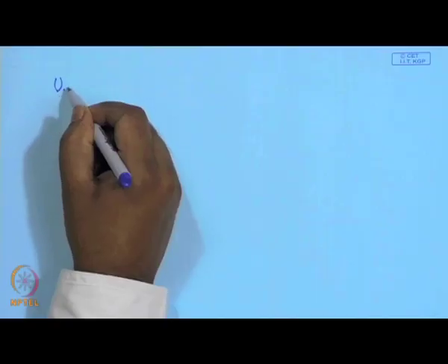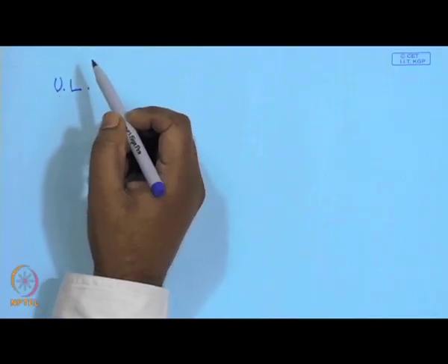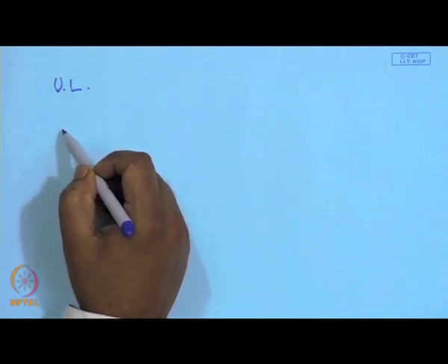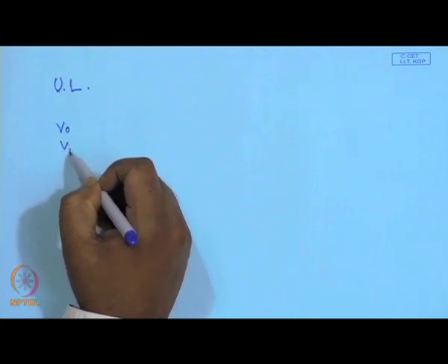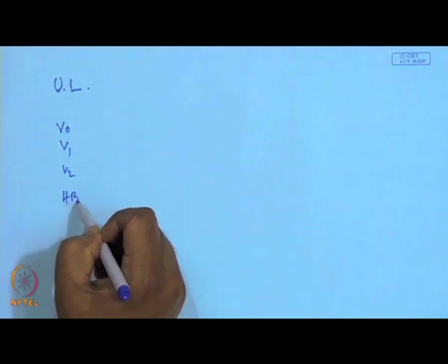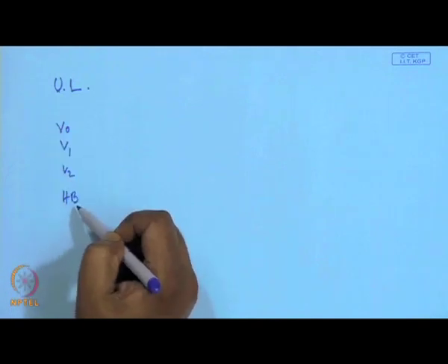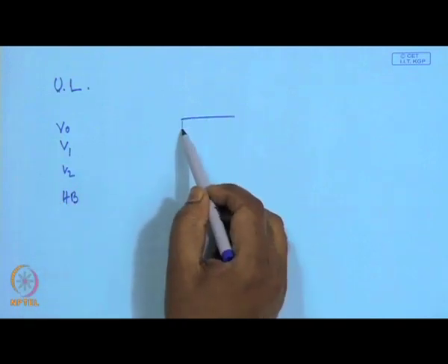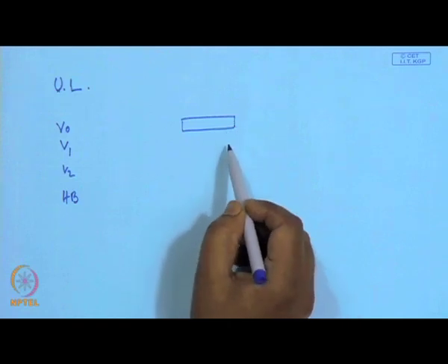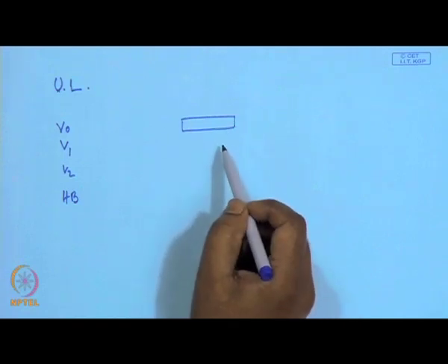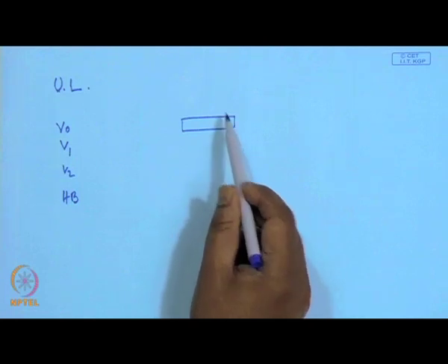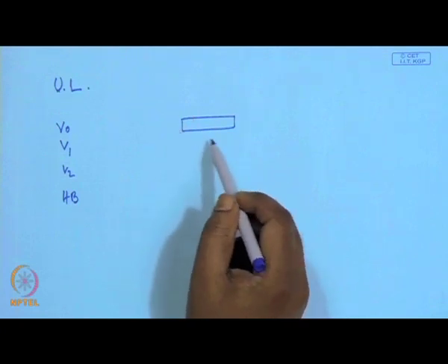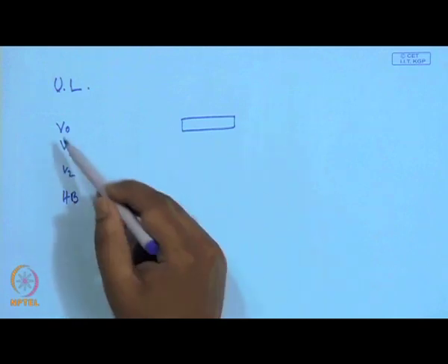Now, other tests are also there, which are done for real applications, guided by UL Laboratories, and they rate materials with different ratings like V0, V1, V2, HB and those things. In this case, they specify the geometry of the sample. These tests are very difficult to carry out repeatedly, and only trained and certified persons actually do the test for comparing materials or giving the rating.